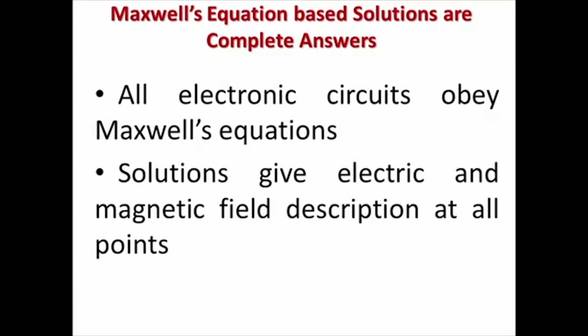But at higher frequency, obviously that is not the case. There we need to consider non-TEM type of propagation. Maxwell's laws get solved there by various modes, that is why power gets transported by various modes, and we will have to solve those problems with the help of Maxwell's equations and boundary conditions.